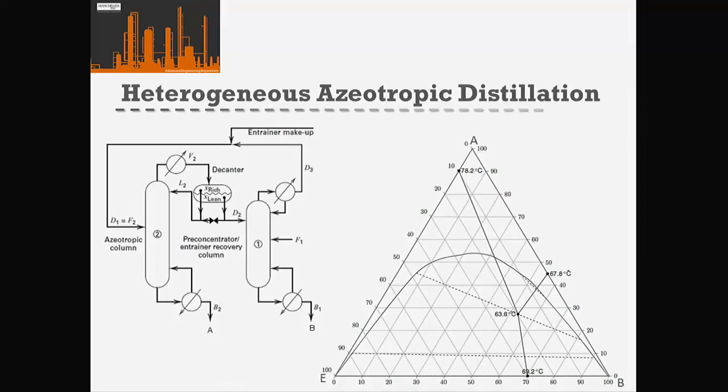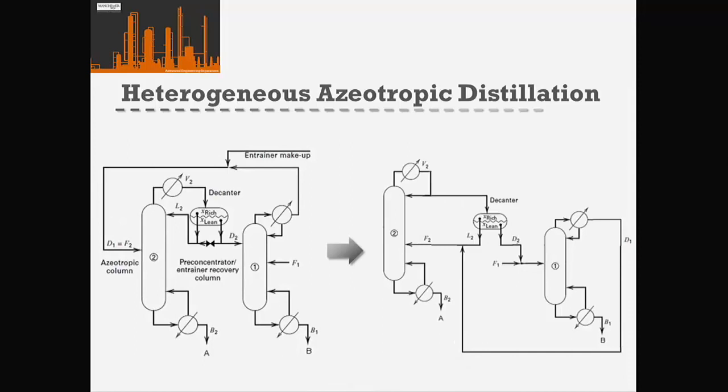And as we mentioned when we were looking at our extractive distillation column, it's much easier for us to think about doing the addition as its own step, separate to doing the separation with the distillation column, okay? So what we can do is modify what we would build in reality into a more simplified distillation sequence where our addition steps are essentially done separately to our separations.